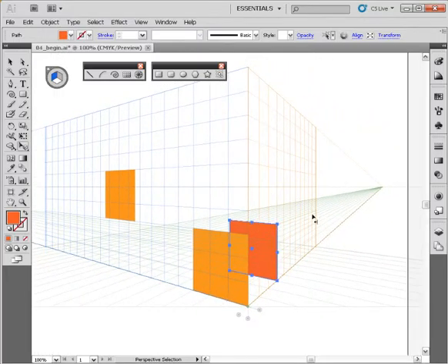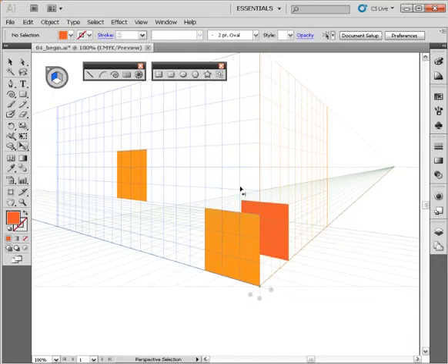So we've created that next side of our cube here, and I tell you what, let's deselect that here, and let's talk about creating maybe this side of the cube right here that goes on our right grid plane. Well, we could come up here and just select the right grid plane from our plane switching widget and just draw it right in there. Or we could make a copy of this one and move it from this left grid plane to the right grid plane.